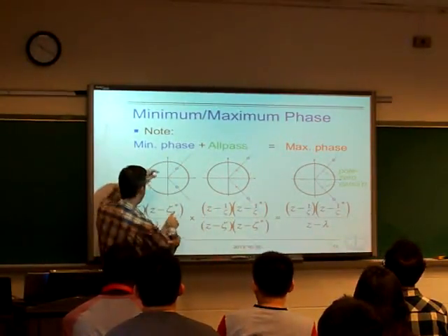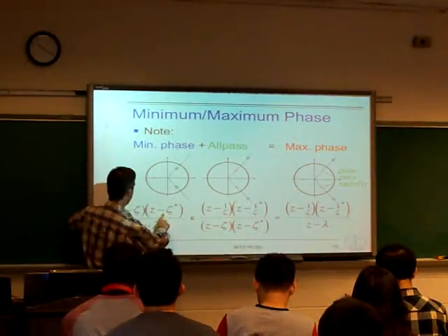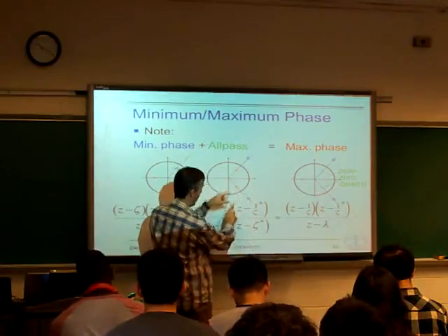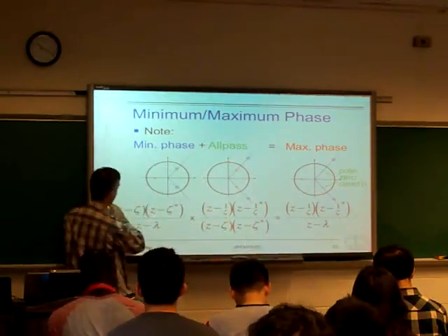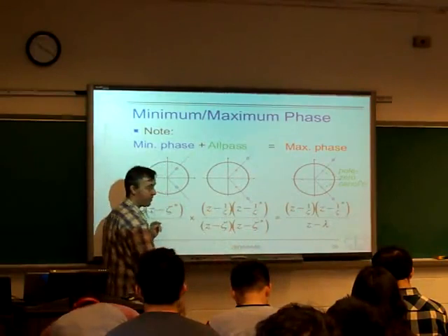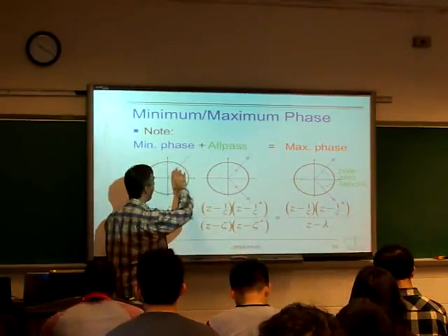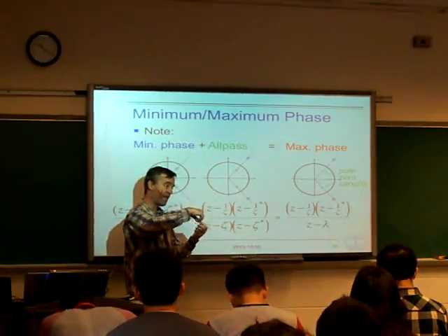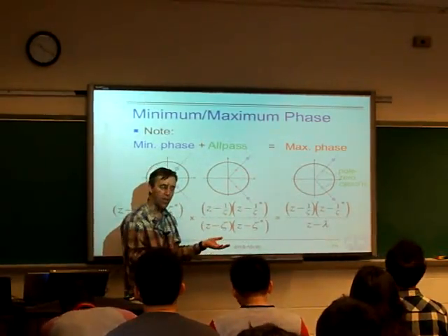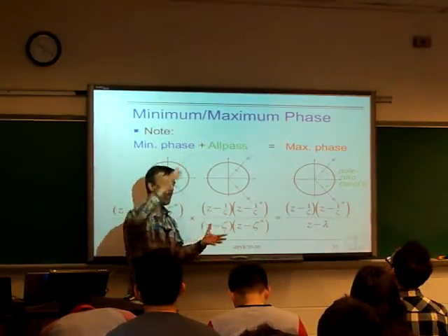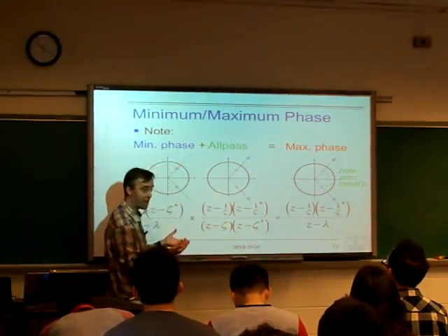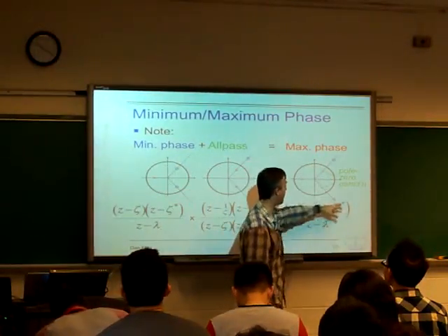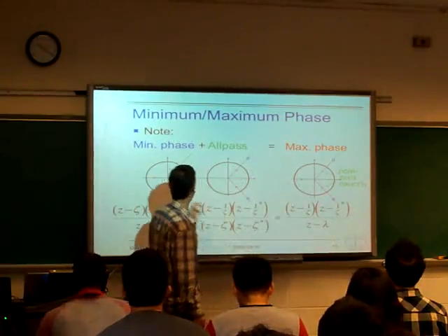The transfer function has these roots, these zeros here, which correspond to these two terms here, and then it has these poles here at the same locations. So just by algebra, we can see that these things cancel out, which is the same as saying that if we have a Z-transform system where we have a pole and a zero in exactly the same place, then they annihilate each other. The thing pushing up and the thing pushing down are exactly in balance, so they disappear as if they weren't there at all. So we get pole-zero cancellation. We end up with a system here, which is the maximum phase version of this.